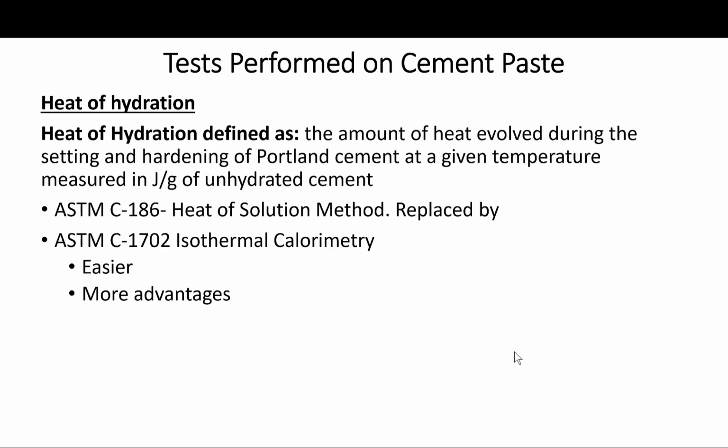The isothermal conduction calorimetry has the advantage of measuring the heat of hydration instantly, from the time of mixing of the cement with water. It's a powerful tool though. I have used it and it's fun. It is, like I said, a useful technique in studying the effects of admixtures on hydrating cement, for example, or any other additive. As I said, it's a great tool in research.